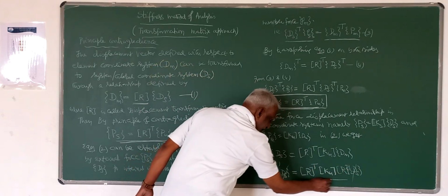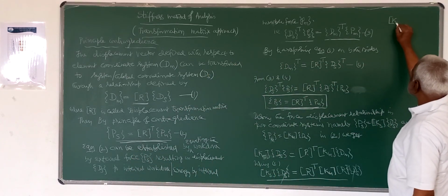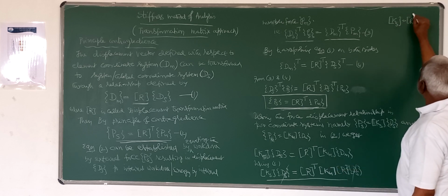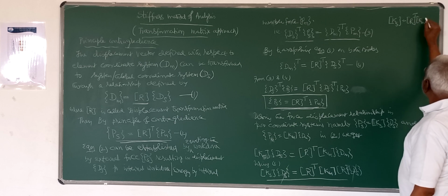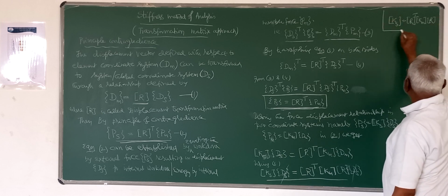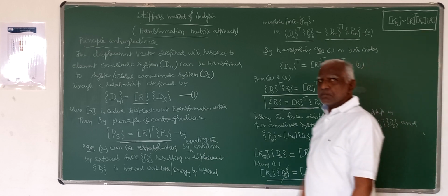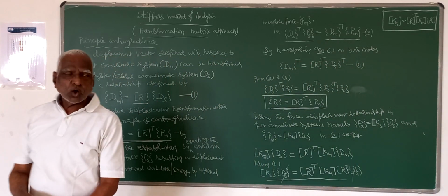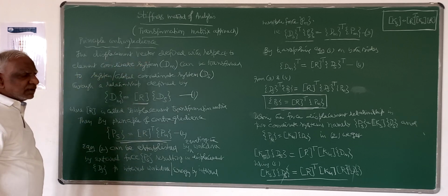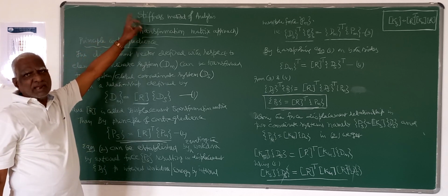Now you have the relationship Ks is equal to RT into Km R. This is the important relationship which relates the element stiffness matrix Km with the global stiffness matrix Ks. That particular equation we are using in the stiffness method of analysis.